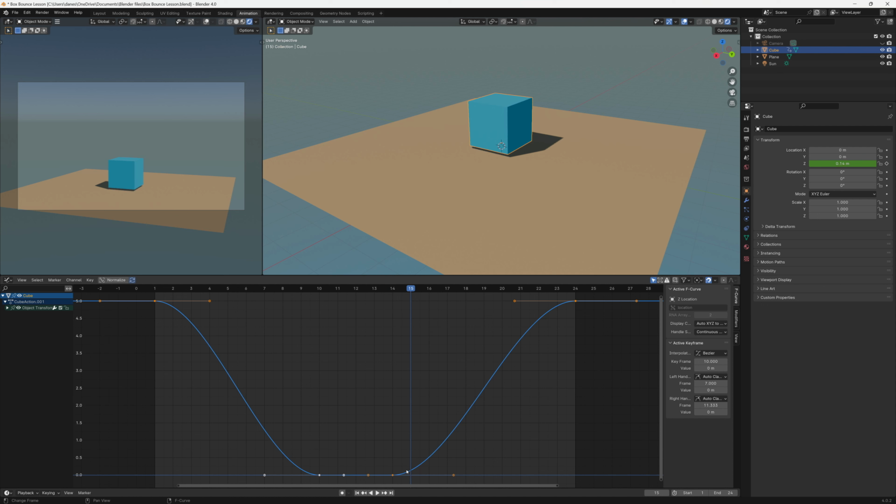Look what's happening. It's also sloping as a slow interpolation. So this is going to bounce up. So it has to be quick. So on 15, it can't be there. It has to be around here already. Okay. So we got to change 10 and 14. We don't have to do anything with 1 and 24. Not unless we want it to slow down at the top, which we will. Okay. So for now, we want 10 and 14. What are those other handles right there? That's the Bezier handle.